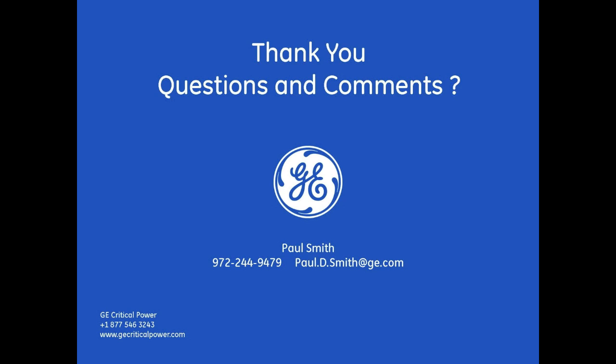But what we have to look at here is that that's offset, more than offset in most cases, by the fact that you've now got reserve time flexibility, which means that you don't have to provide the full 8 hours or 4 hours for every piece of equipment. So you can reduce the battery capacity on many of your pieces of equipment in the modern facility, and the flexibility of the distributed architecture allows you to do that. So in most of the examples that we've looked at, the battery capacity actually ends up being significantly less, not more.